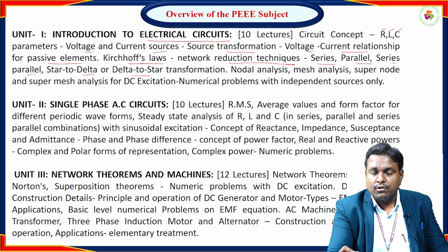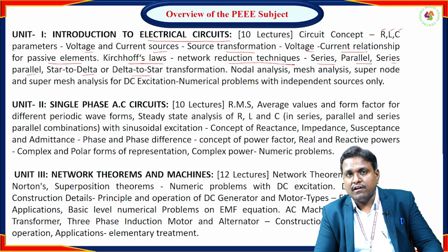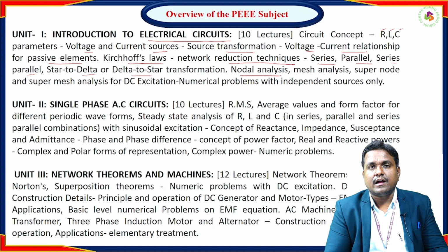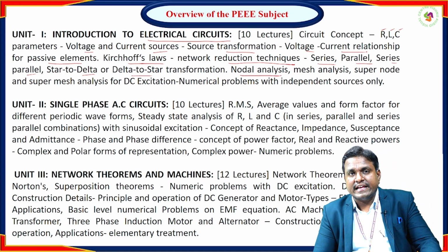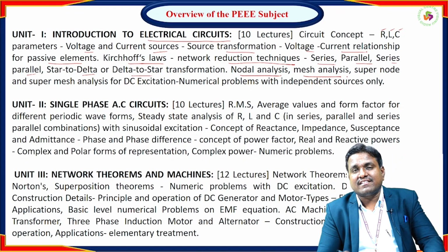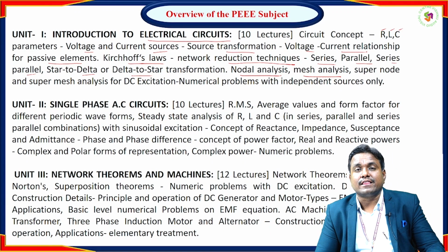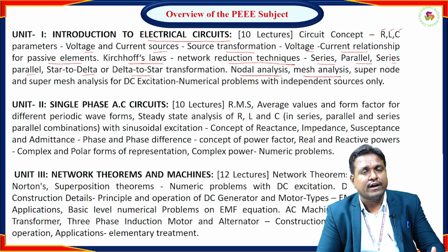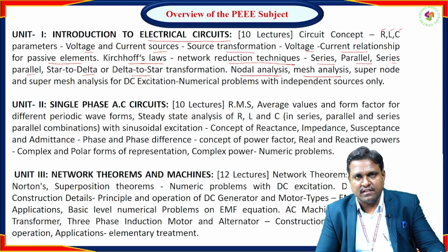Next, we are going to have the application of the Kirchhoff laws, that is Kirchhoff's current law, which is the node analysis, and the application of Kirchhoff's voltage law, which is the mesh analysis. So in the node analysis, we are going to find the node voltages, and with the help of those node voltages, we are going to find the response in the circuit.